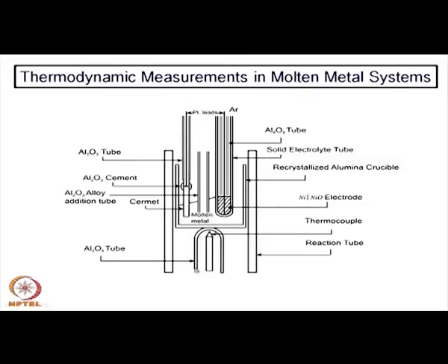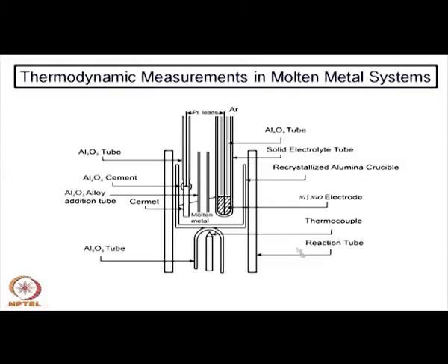This is a thermocouple which just measures the temperature, because if you remember the Nernst equation, you also need to know the temperature. So, the precise measurement of the temperature is also important if you want to measure the oxygen partial pressure by this process.